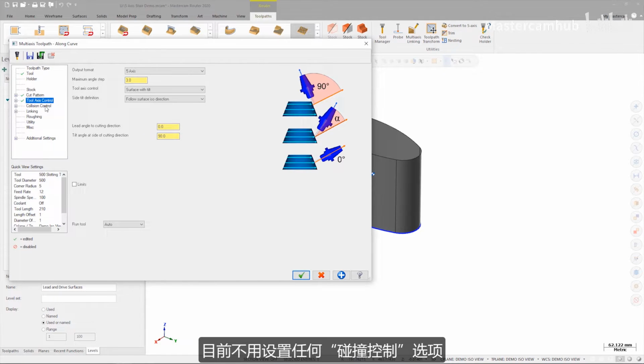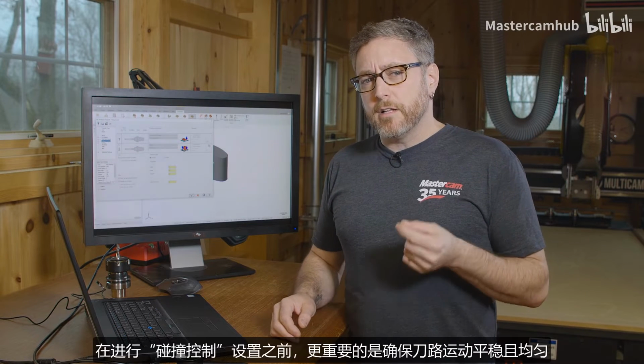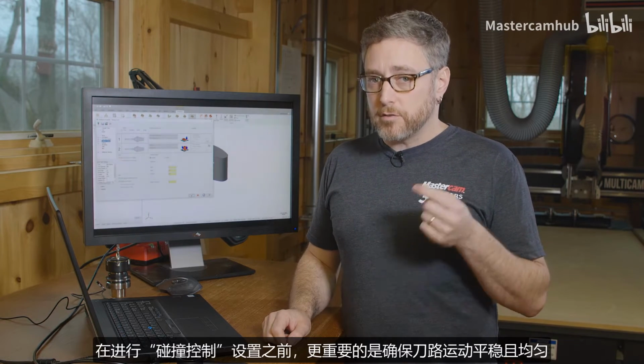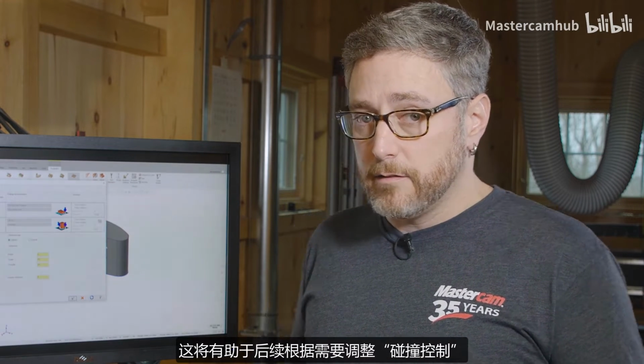We're not going to set any collision control options at this time either. Before worrying about collision control settings, it's more important to make sure that the toolpath motion is smooth and uniform. This is going to help make collision control easier to set up later when we do need it.